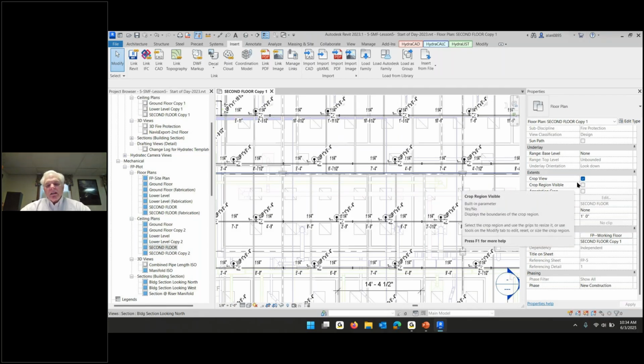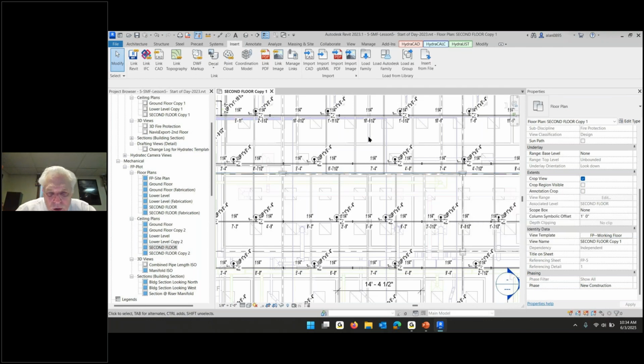And then the other thing is the by type. Walls participate in that cut plane to decide whether the doors in them or the windows in them should show when we show you the walls. And you'll notice that the door swings are gone because cutting the wall through at 13 feet doesn't go through the door, so we don't show the door. Same thing for the windows.